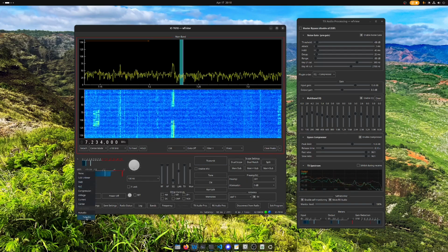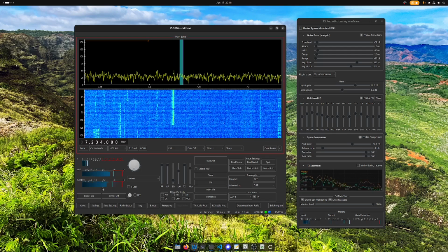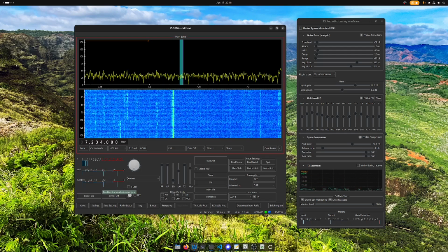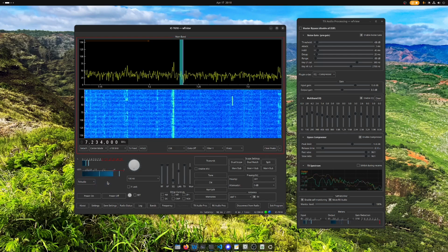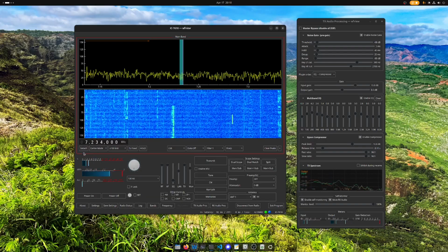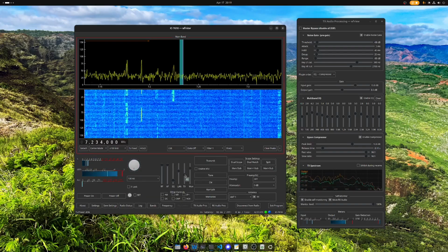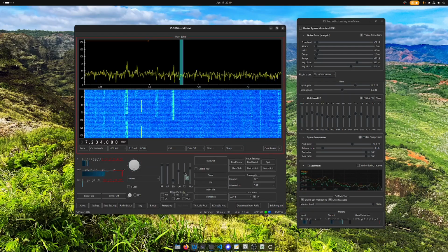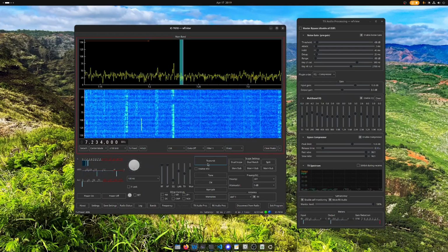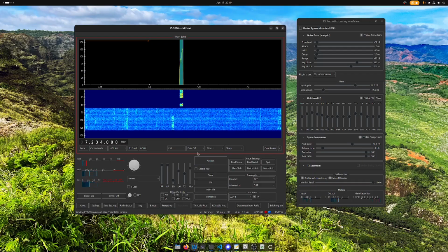You may or may not know this, you can double click here and select transmit audio, and you'll see that metering even if you're not transmitting. That's okay. And I think actually I want to change over to ALC. That's right, okay. So ALC is what we want to adjust here. I'm going to put the power at 50 watts into the dummy load. That should be good. Okay, so now we've got ALC selected.